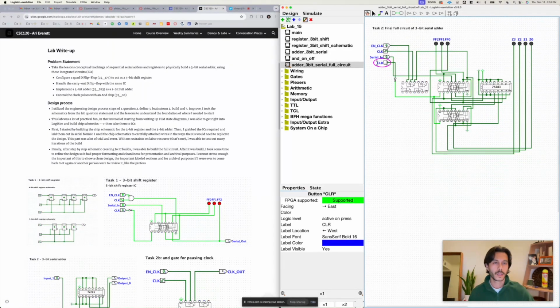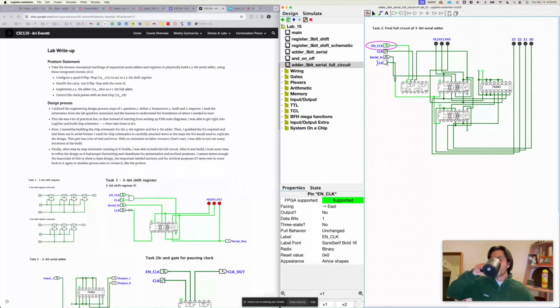So let's go ahead and turn this on here and show a demonstration. Let's enable it first of all, like a microprocessor would. Let's say we select the adding function for the processor to do. So turn that on. Let's add in the number 001. Again, it's right to left, least significant to most significant. And let's input that. So serial input will have low. So I'll just act like there's zeros going in.